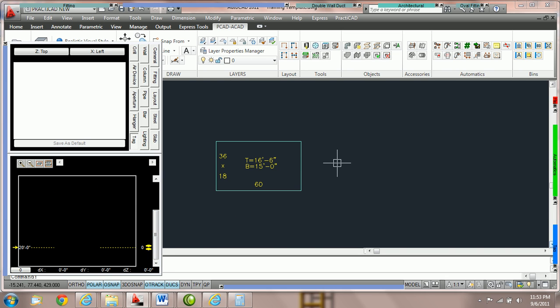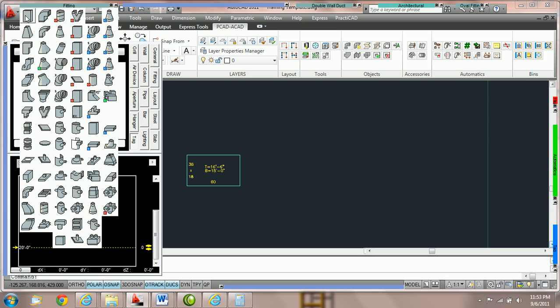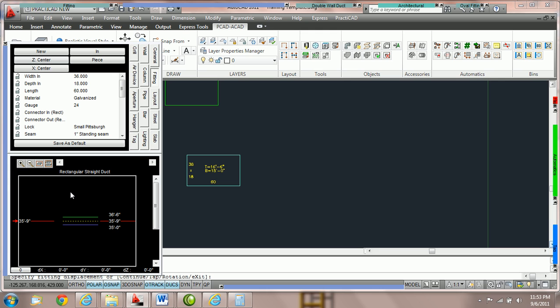Now what I'm going to do is place one more piece of duct above the slab by 5 foot. I'm going to grab this duct, I'm going to come down, and notice I've only got 3 values again. It's because we haven't set anything to relative bottom. We undid it. Second we check this to blue, 3 values appear. And now what we want to do is ignore the absolute 0 values.